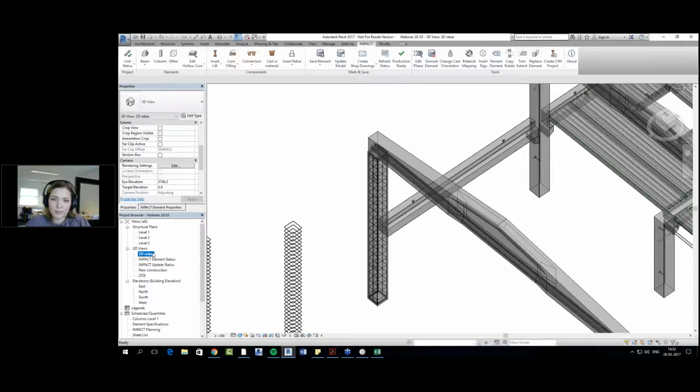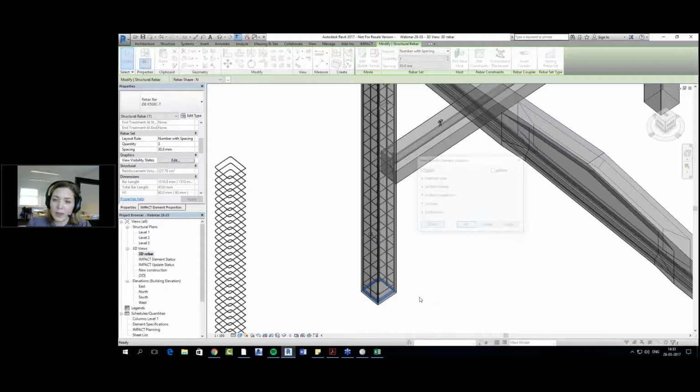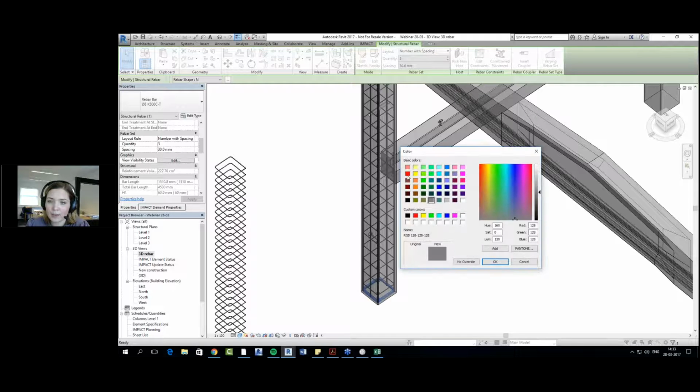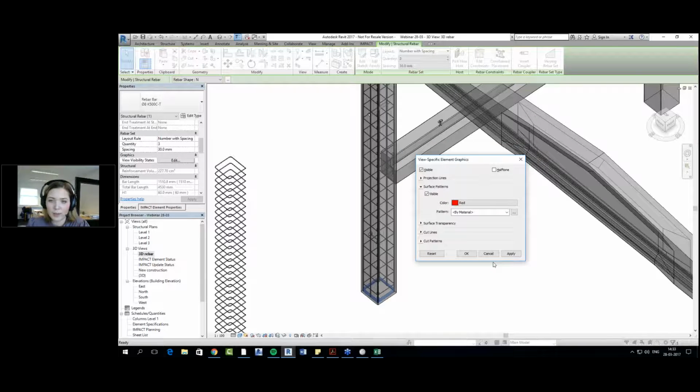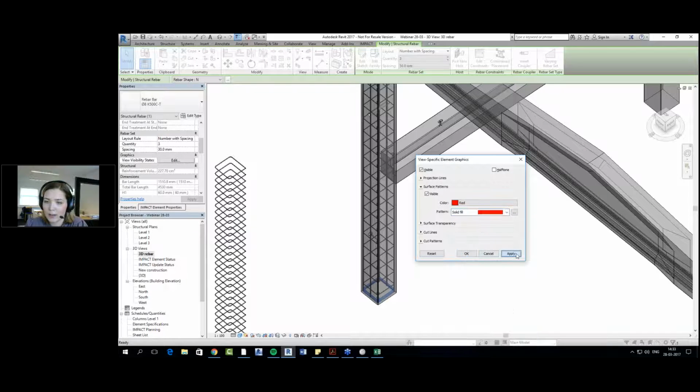or they create some kind of sheet with the legend with what color means what. They can, for example, say, let's take this reinforcement group, and they want to color it out just for the future, so they have revision on here, or they have to check something, or mark out different reinforcement groups. So I just say that the pattern is solid and apply.